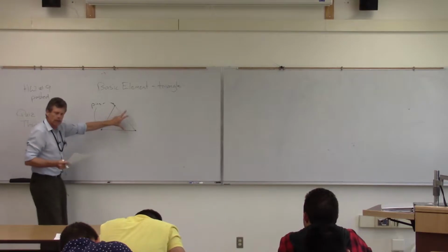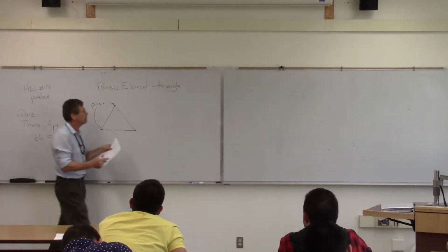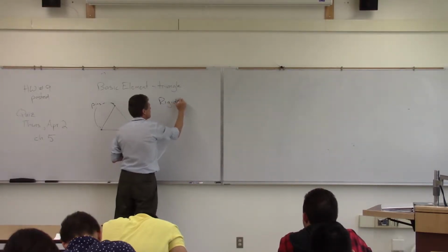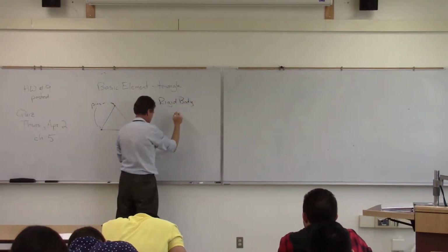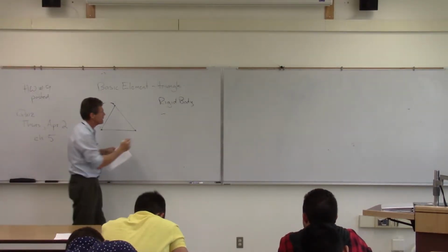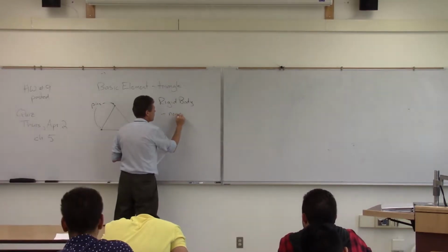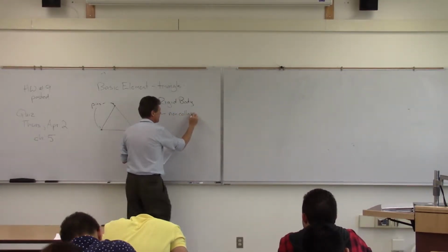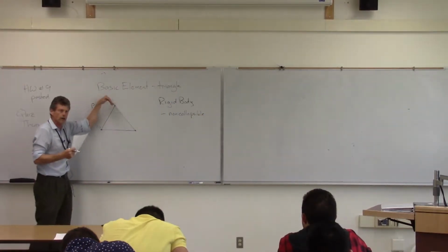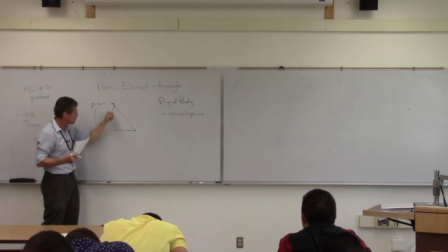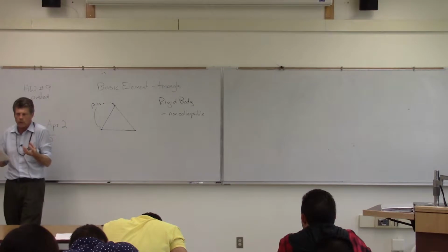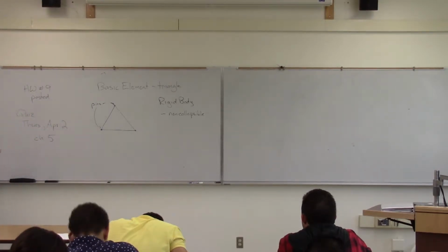But the nice thing when you think about this particular truss, it meets our definition of a rigid body in the sense that it's not collapsible. If I push down on this, if I pull on this, if I go this way with it on one of these ends, those members, since they're all connected into this pin, what we have is a rigid structure.